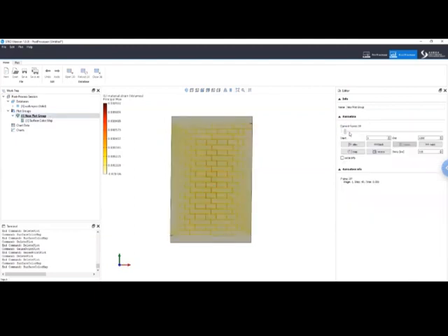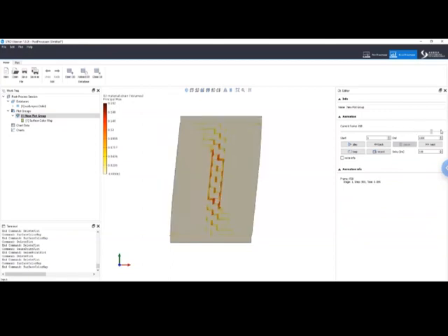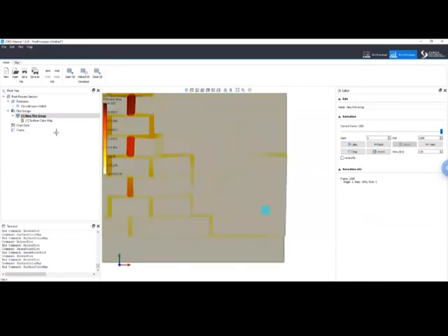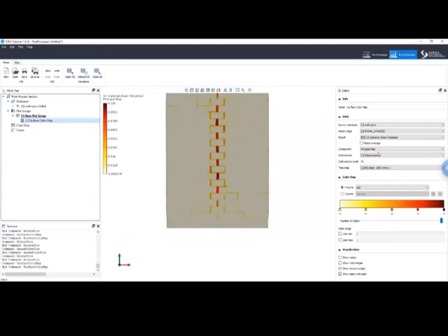Let's see what happens. So you see, in this case, you see a crack, the opening of the crack actually, and also it is reclosing. So at the beginning, when everything is elastic, the strain is almost uniform. Then you have localization at the top and bottom toes. And then only at a later stage of the analysis, you see the diagonal cracks in the middle, up to a final failure of the model when the crack reaches the corner here. Okay, so let's go back to the damage.